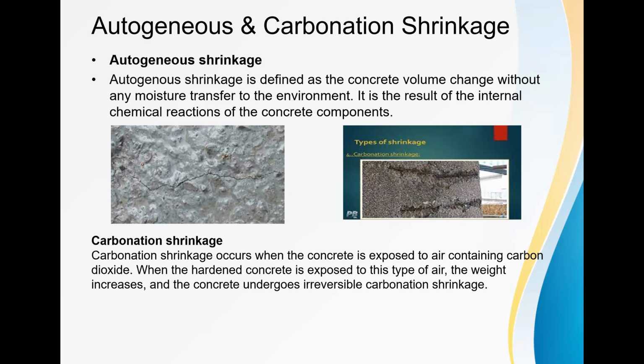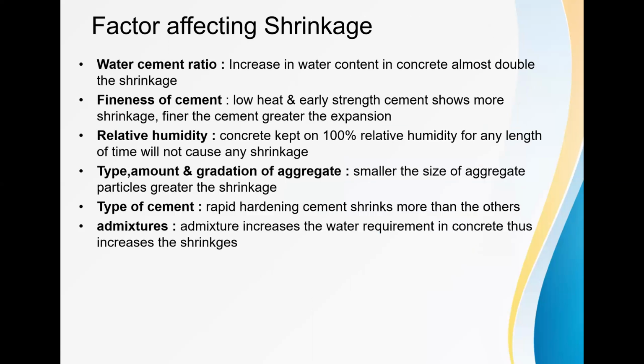Then what do you mean by carbonation shrinkage? Carbonation shrinkage occurs when the concrete is exposed to air containing carbon dioxide. When the hardened concrete is exposed to this type of carbon dioxide air, the weight is going to increase and the concrete undergoes irreversible carbonation shrinkage. It is called carbonation shrinkage.